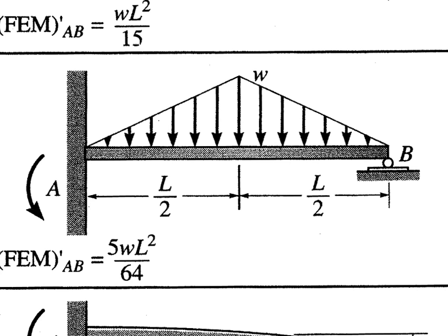This one, again, is fixed in the wall, so it's like a diving board. Think about a diving board, okay? You go to the end of the diving board, you jump on the end. Does the beginning of the diving board move at all? You better not, or else it's going to flip over and hit you in the head. What moves? The part you're jumping on. When you jump on the end of the diving board, it bounces up and down, it fluctuates. This end, though, is not moving. It's not able to rotate. That's this end right here of the diving board. So this prevents rotation, whereas over this end, this thing only prevents you from moving down.